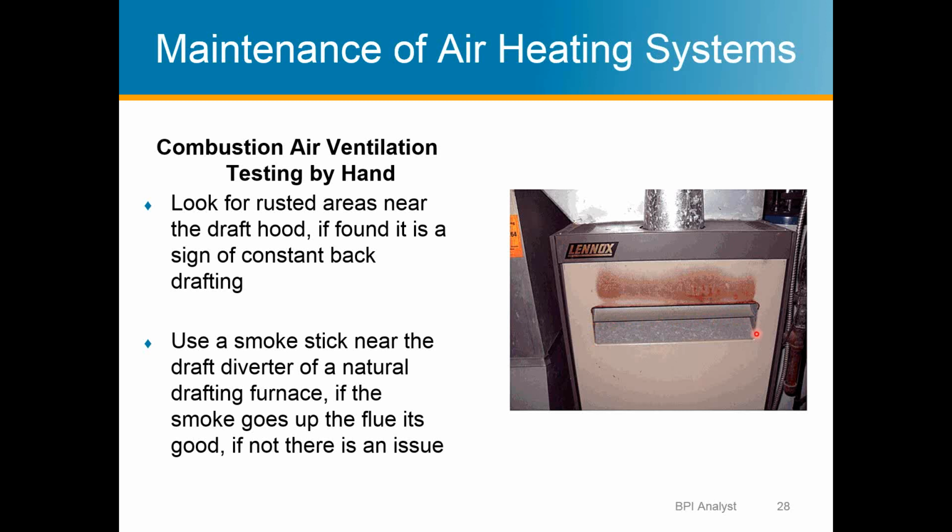Spillage is okay up to 60 seconds. At 60 seconds and beyond, it's a failure for BPI. So you can either use a mirror. A mirror is a good indication that it's spilling, or you could use a smoke stick, which is a good indication that it's passing. So use whichever you like, or use both if you're not sure.